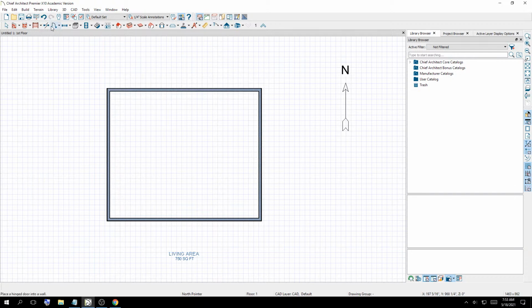So let's add a door. Okay, so if we drop this down, we have standard hinge door. And you're going to see a shadow of the door here before I commit. I'm going to have it off center. Okay, at this point, I don't specifically care where you placed it. We can put some dimensions in a little while. So we have a door there. Let's put a back door approximately here. And this is a fairly small house, so I don't believe that we really need a side door at this moment. Front and back are fairly close together. They're literally 25 feet apart. But you can add your own side door if you needed, and so forth.